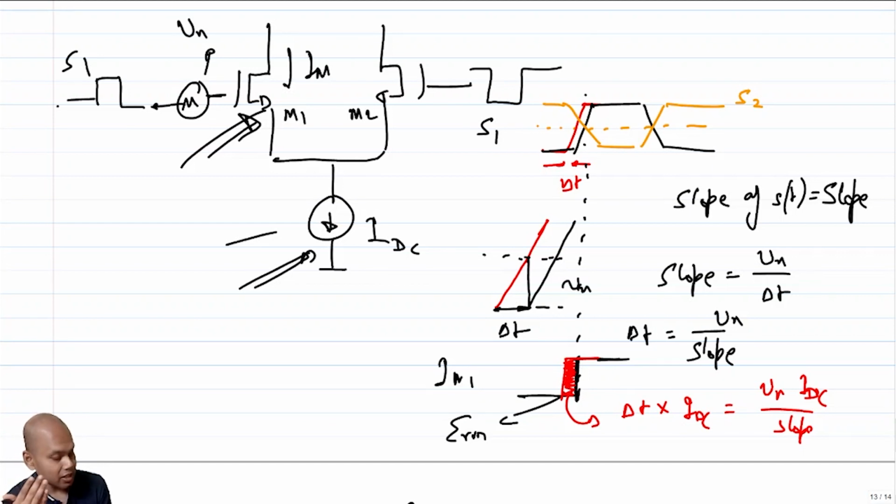Again, this is not a generic suggestion. This is a suggestion based on the technology or the topology that you have. Do characterize the technology that you have to see the strength of the PMOS versus NMOS, and also the flicker noise profile of PMOS and NMOS, right? Based on that, you can take a call.